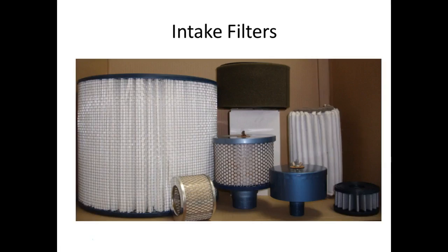Filters, intake filters, everybody okay on those? A lot of problems I've seen: people run lawnmowers and the air filter gets stopped up and it doesn't run right, so they take it off. Then the thing runs maybe a couple more years and it starts using so much oil it can't be used anymore.